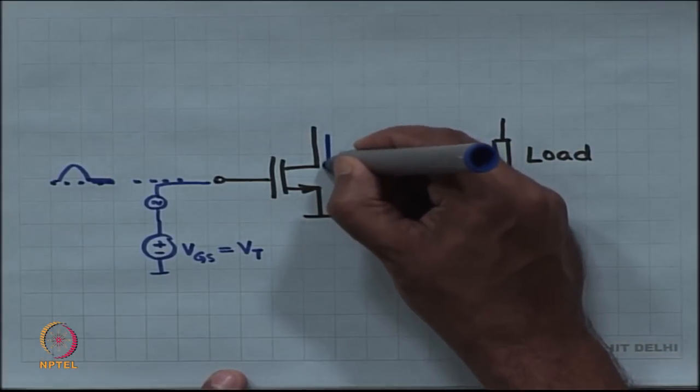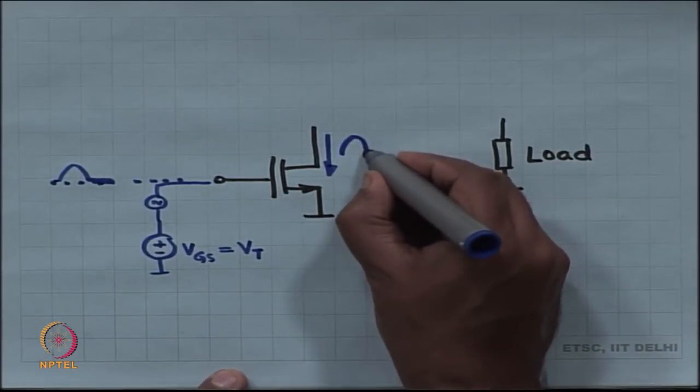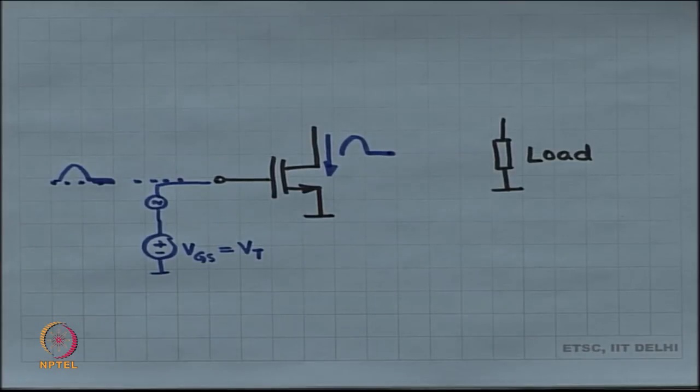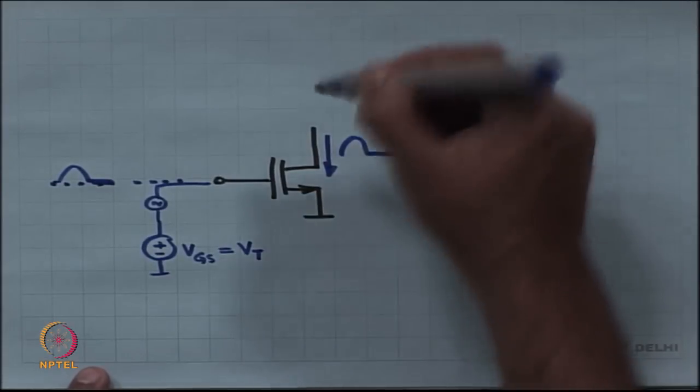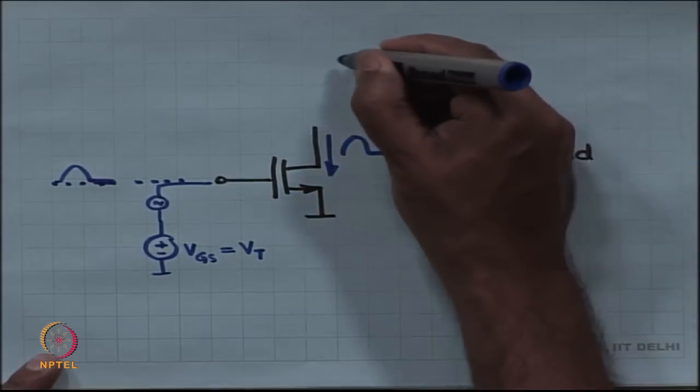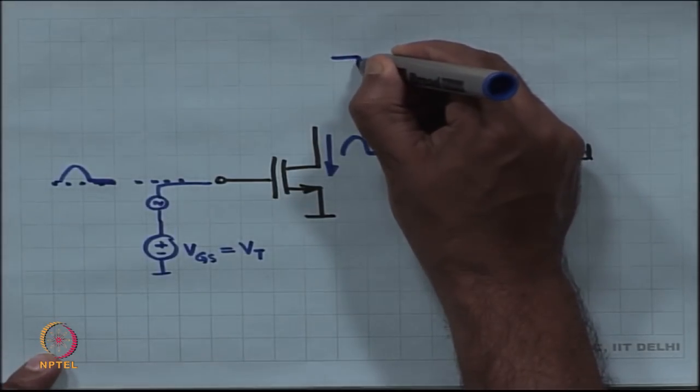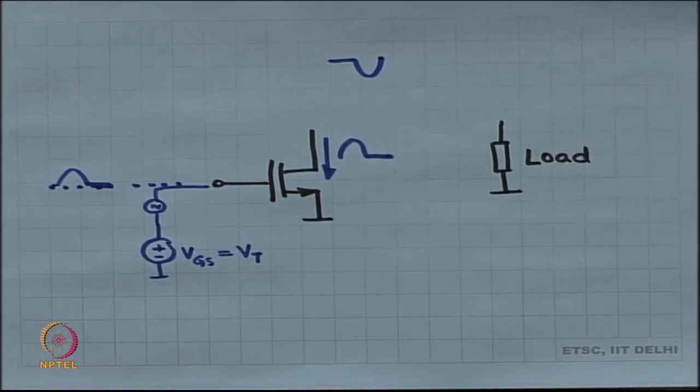Okay. So, the shape of this current is this. Fine. What if I make one more amplifier? Okay. So, what if I make one more amplifier where the shape of the current is this? Is that possible? I can implement it easily with another class B PMOS amplifier.